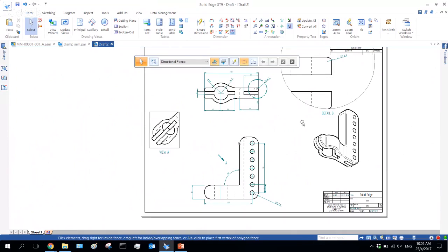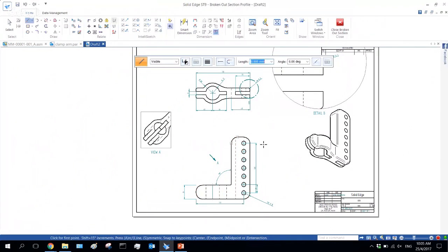And the last thing I want to show you from the drawing part is I want to see the cross section of this 3D drawing over here. So how to do it? In Solid Edge, we have the broken view, equal broken view. Just a few steps, select over here, and we need to draw some sketch of the broken.